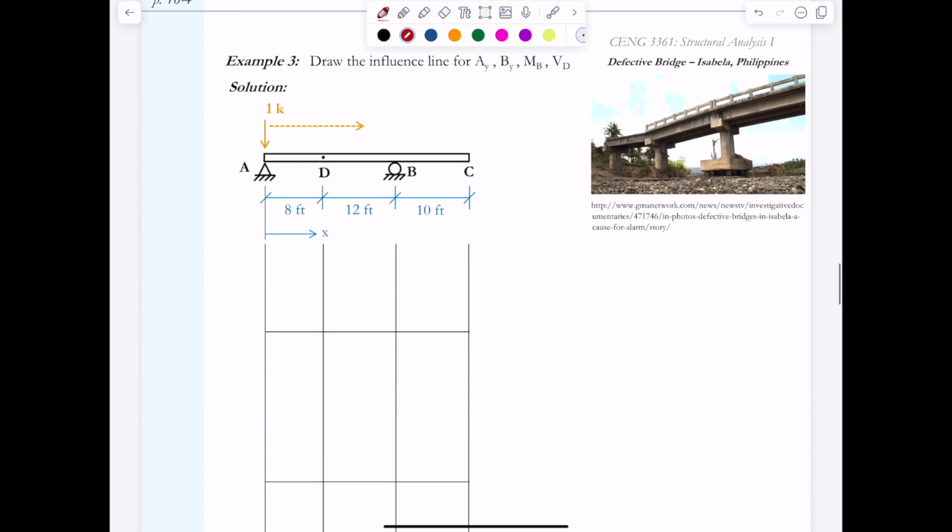All right, so here in example 3, which again is the same as example 2, just keep that in mind. I'm going to look at the influence line for AY, and I'm going to draw in my structure. Now I'm going to erase that support at AY and move it up 1. If I do that, what would the deflected shape be? If you go back to the little video with the connected pieces, you see that it just moves something like that. Now we can use similar triangles to facilitate the calculation of all of these points.